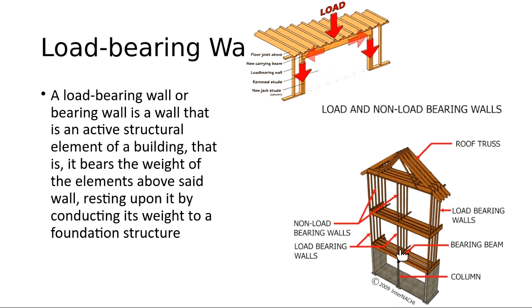So this is a load-bearing wall. See, there's a column down here. So this load is coming all the way down here. I don't know why they're saying this is a non-load-bearing wall, but the load is coming down all the way to the center. If I had another wall coming in this direction, that would be a non-load-bearing wall because it's not taking any load and transferring it down to the foundation. So these exterior walls are transferring the load down to the foundation and footing.